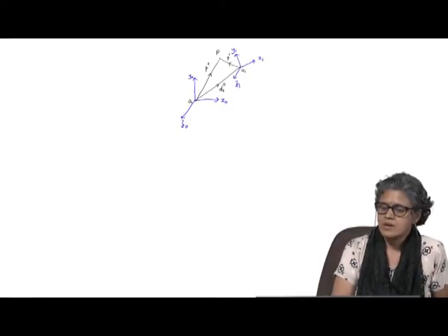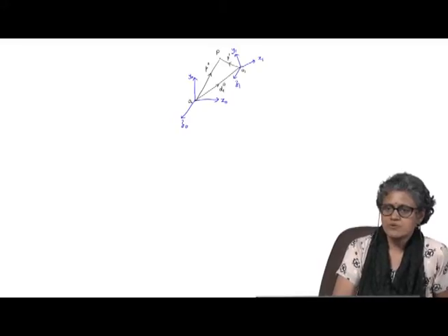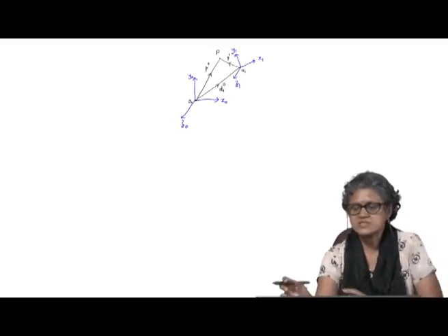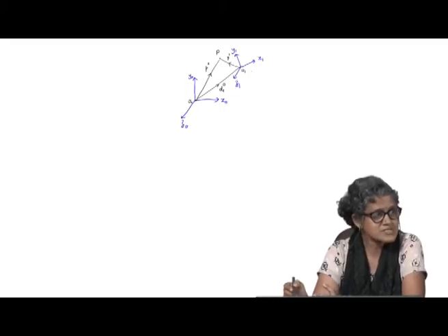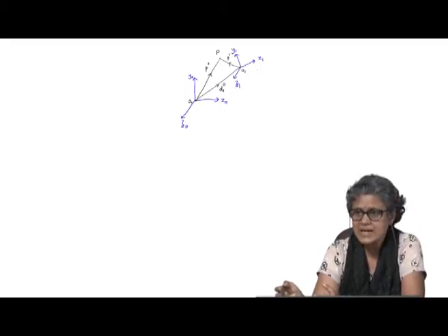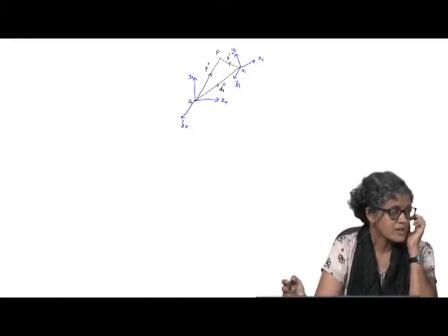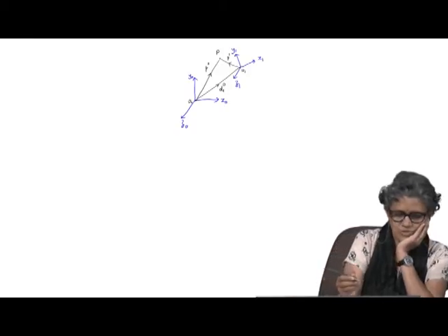Okay. Typically, when you have two coordinate systems, if the coordinate systems are parallel, then I could say that P0 equals D10 plus P1. However, when the coordinate systems are rotated with respect to one another, you cannot directly add the two vectors. I cannot add a vector expressed in coordinate frame 0 directly to a vector that is expressed in coordinate frame 1. So, this